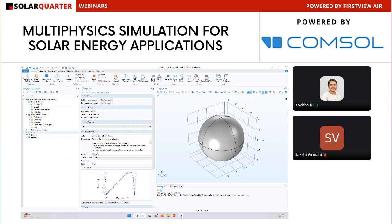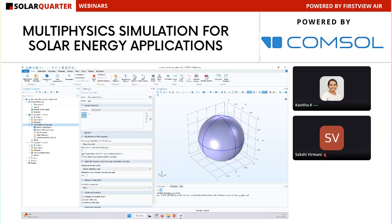So here in this example, we are modeling the solar cell with ray optics. So what we are doing is we are actually going to give incident solar rays using the ray optics or the geometric optics physics interface of the ray optics module.